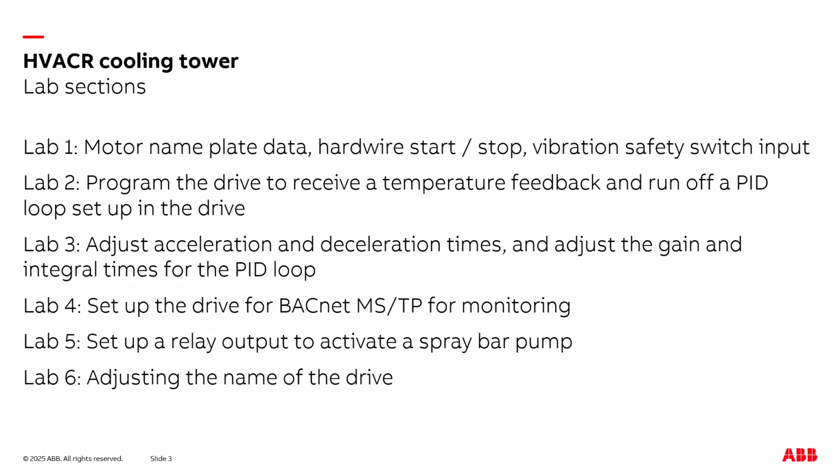In lab 4, we're going to cover how to set up the drive for BACnet MS/TP network connection for monitoring purposes only. In lab 5, we're going to set up a relay output on the drive to be connected to a spray bar pump on the tower. This will allow the tower to operate a spray bar pump depending on the temperature of the feedback signal that the drive is receiving. And in lab 6, we're going to adjust the name of the drive. So instead of it just saying ACH580 on the drive's control panel screen on top, we could set it up to anything custom we want, such as Cooling Tower 2.